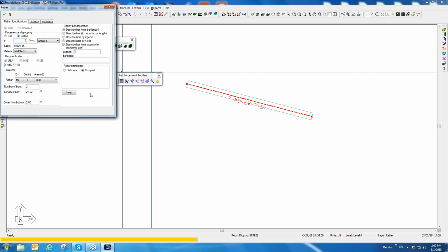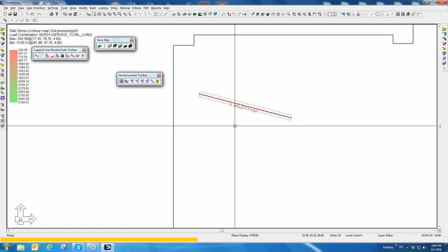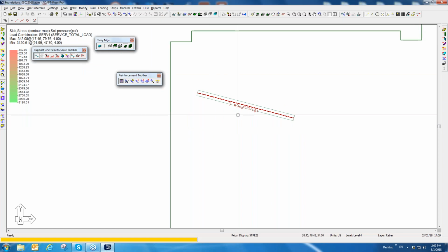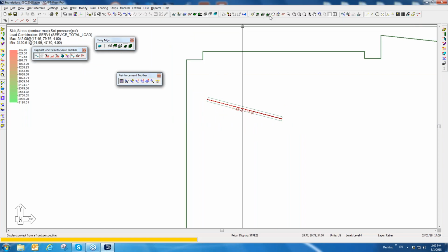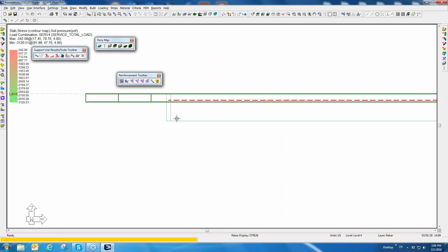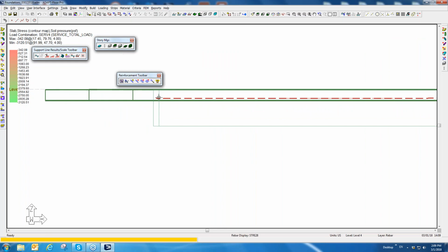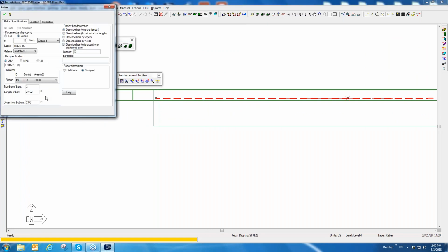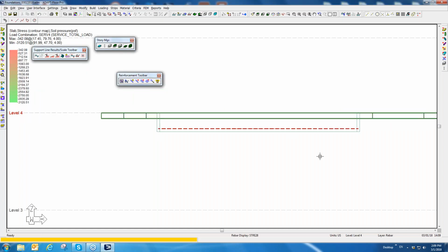So my thought might be that the cover is referencing the bottom of the beam. But in reality, if I turn this back to a side view, the rebar input always references the slab. So you see this bar is actually 2 inches above the slab. It's not where I think it is. So if I offset this by, let's say, negative 16 inches, then I push it down into the beam. So you have to input a negative cover for the bar to be in the beam.